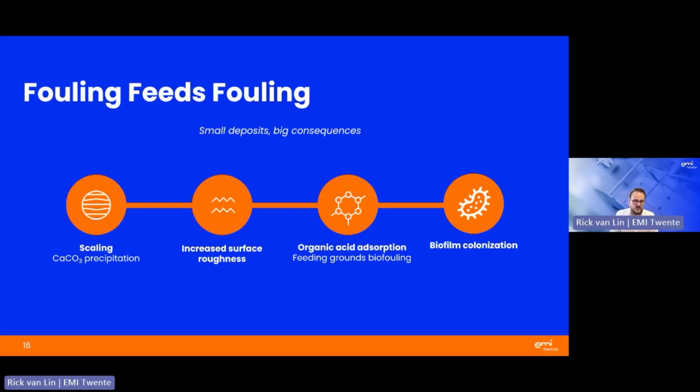So it's pretty difficult to draw conclusions on the type of fouling based on process indicators such as pressure drop, cross flow, etc. alone. And therefore, an autopsy is a great tool to see if the chicken or the egg came first, and to adjust your process accordingly.